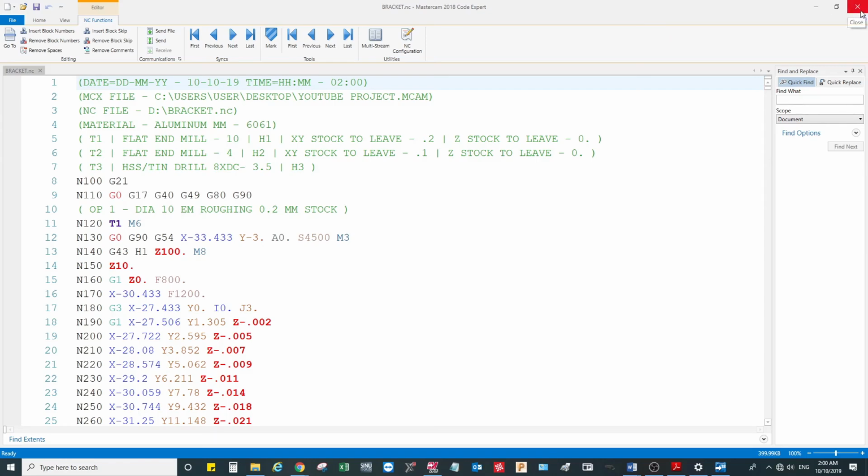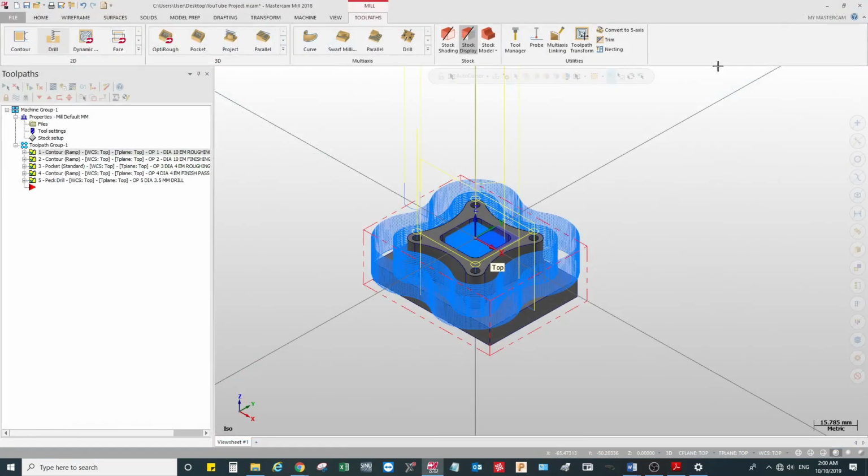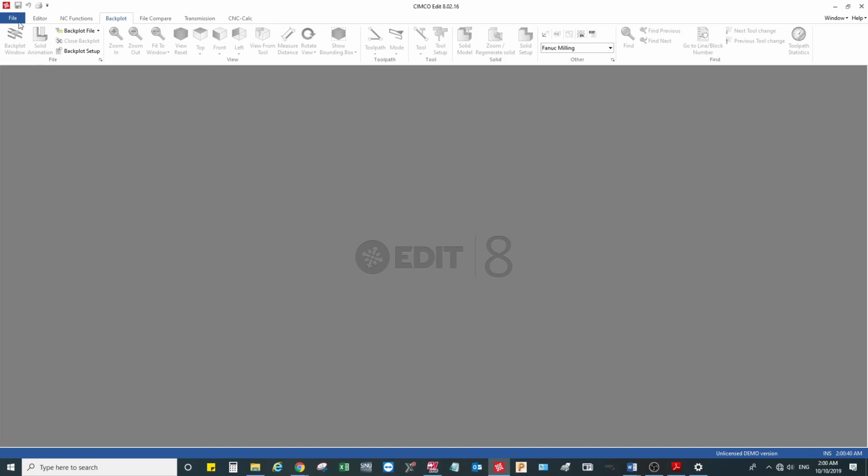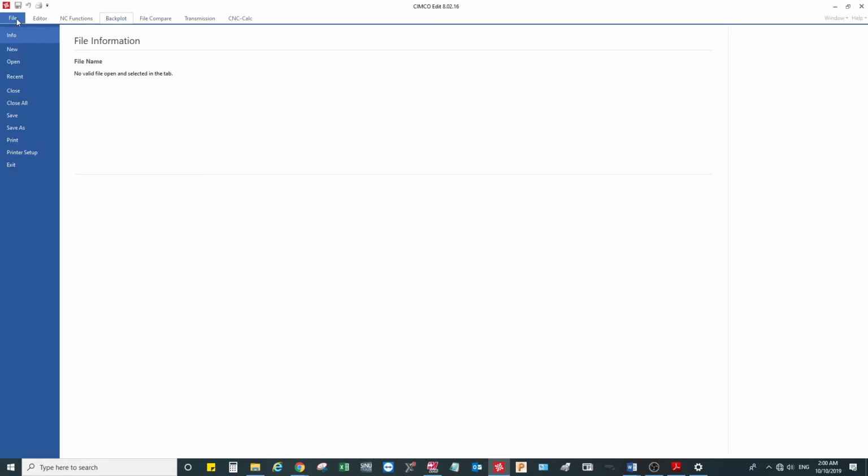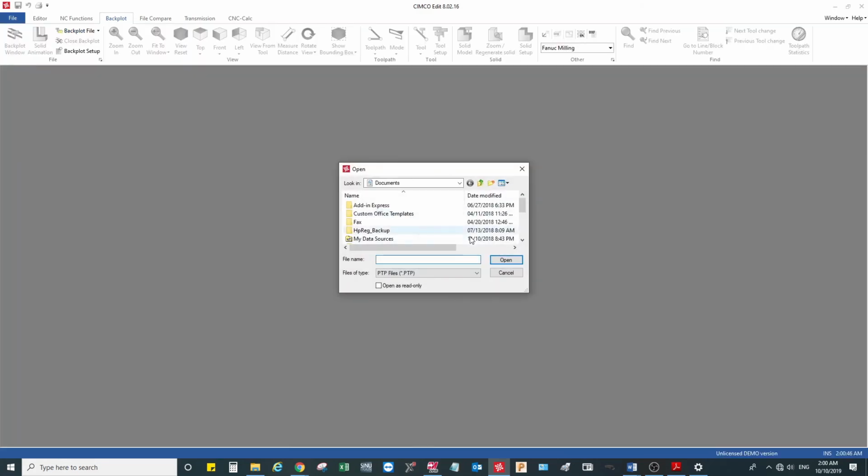It's asking me for the top of stock, it's the same. I'm going to click on absolute command for this. It's asking me for the depth, so it's pretty easy in here. You just go here, hover, and then click on this line entity, and then you will get to know, okay, it's 10 millimeter deep.